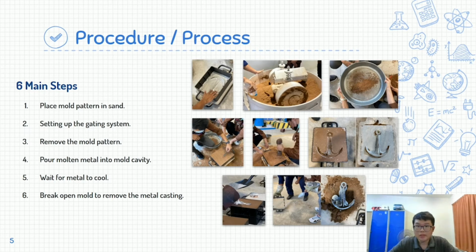Now let's proceed to step 2, setting up the gating system. In this step, we are going to pack the pattern into the sand mold of the drag part and ram it hard to flatten the surface of the sand.